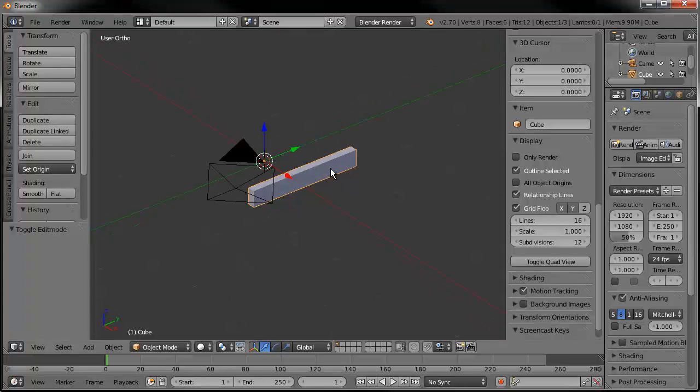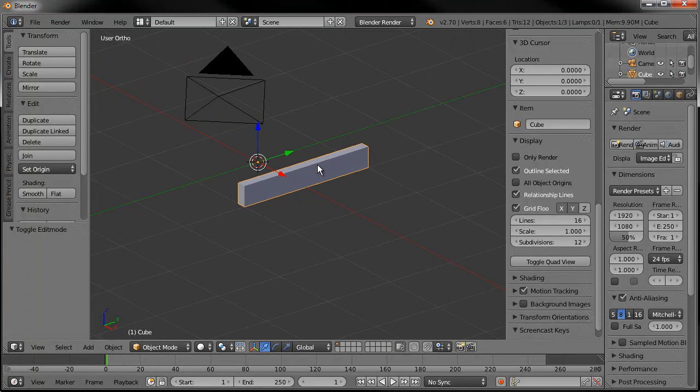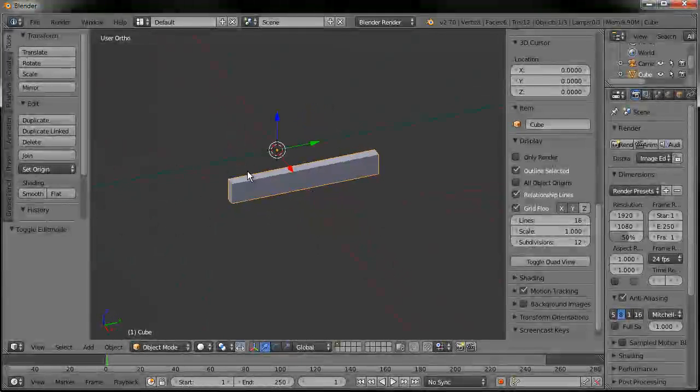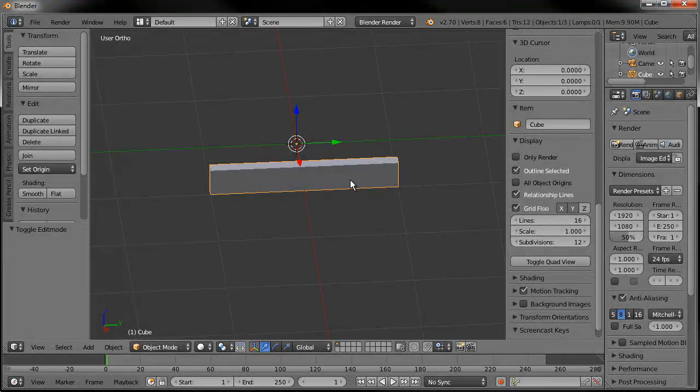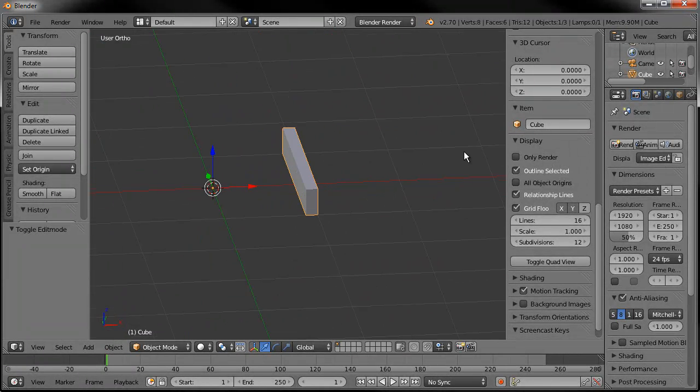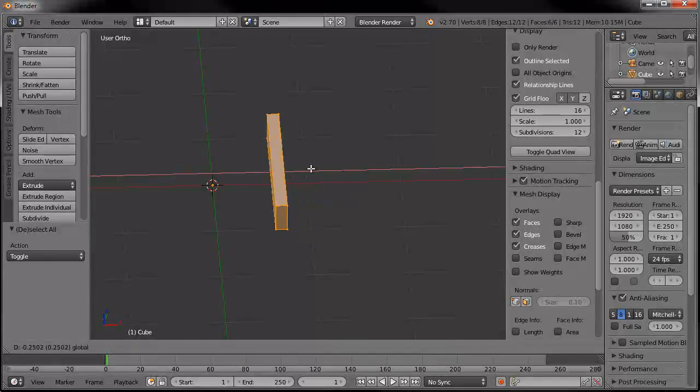Now, the height and width, the 2x4, those are inaccurate as far as the actual dimensions go, but the length is always going to be exact. So if you buy a board at the lumber store that's 2x4 by 8, the 8 feet will be correct. It will be 8 feet exactly long. They might have a variation of a 1/4 inch or so, but overall it will be what it says, 8 feet. But the 2x4 part will be 1.5 by 3.5.